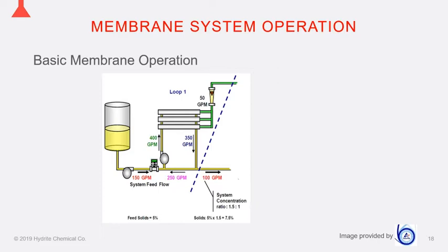So as the diameter of that vessel increases, so does the need for the flow that goes through it. It's like cleaning of any pipe. The bigger the diameter, the higher the flow to get the velocity that you need to clean it. Okay, so for my example here, I have 3 8-inch housings. Each one of those housings needs, say, a minimum of 100 gallons per minute flowing in. Now, in each of those housings, there probably is 3, 4, or 5 membranes sitting in there, all of which will need flow across them.